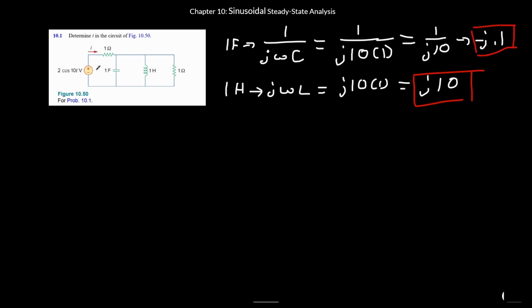But of course, we cannot forget our resistors as well. To find the total impedance of the circuit, we'll need to add the resistors together with the inductor and the capacitor. All I have to do is add all the components as if they were resistors, since they're all converted into impedance.